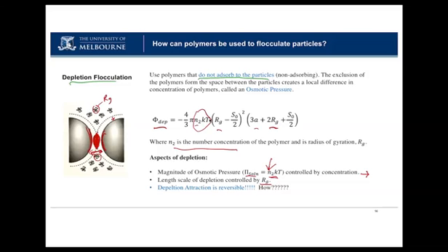You might have particles that you want in a flocculated state at one point, but when you go to use them and dilute them, you need them to be dispersed. So depletion attractions can be very useful in making products that change their stability depending on the concentrations of polymer around. Depletion and flocculation are very good for engineering what are called responsive products or complex fluids. It's a pretty cool bit of thermodynamics. Change the concentration, and the depletion force goes down. All right.